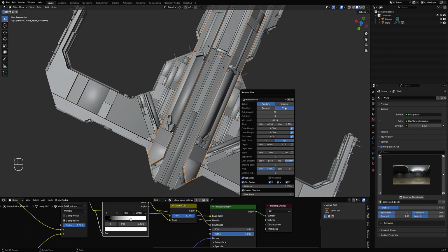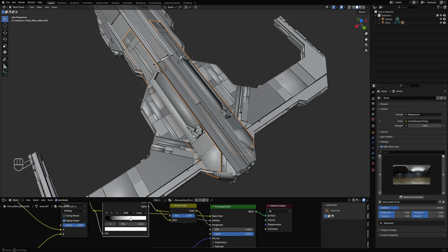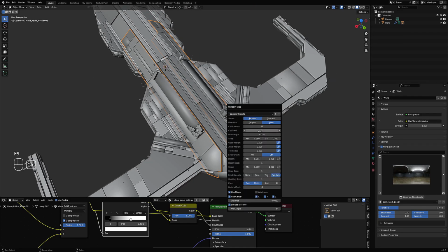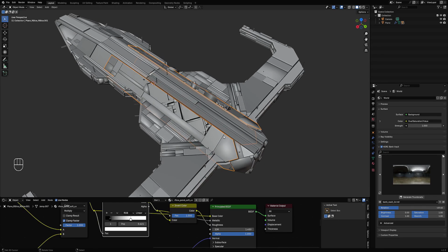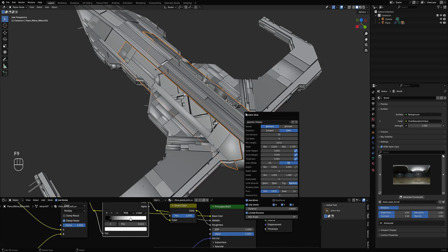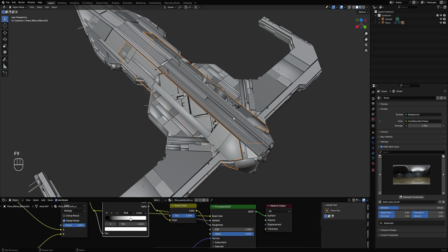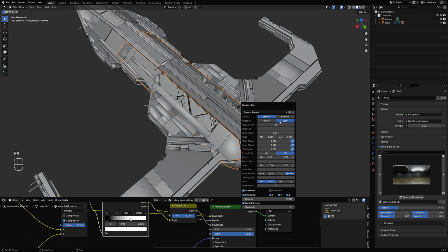So be careful with this because if you change the angle like that and then randomize, for example, because it's a redo panel, it's actually going to reevaluate and rerun the script, and because it's using the view angle, it's going to use the new angle that you're using. So if you're using this and you like a particular view angle, do not change the angle or rotation of the viewport.